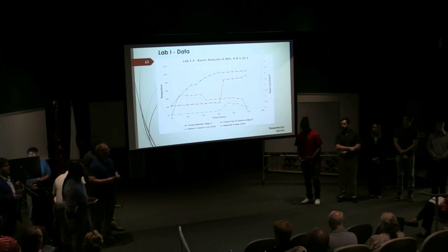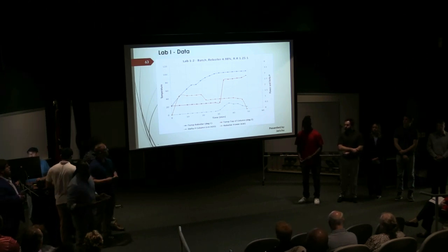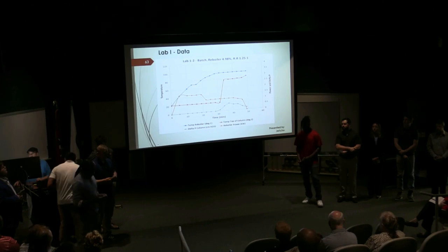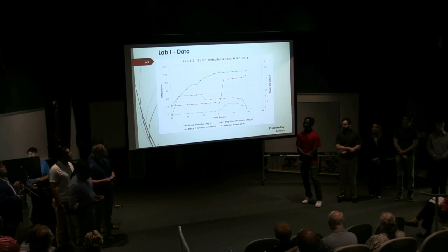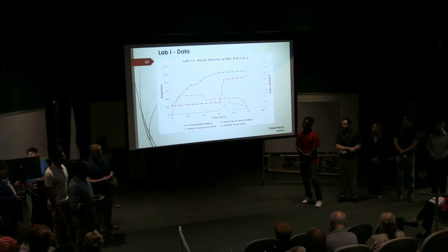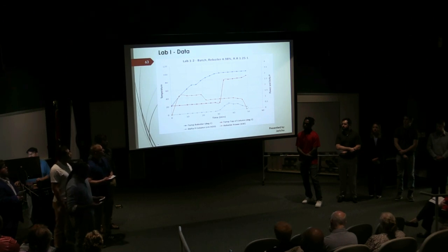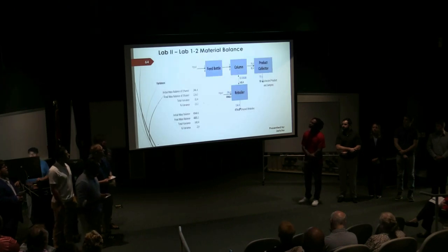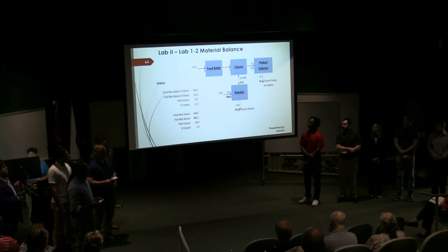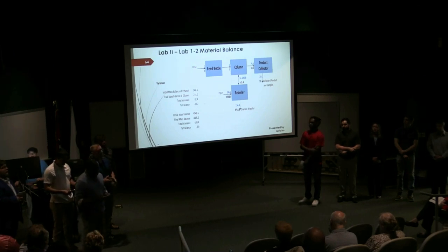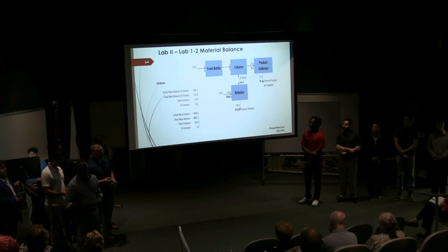In our next experiment, we raised our reflux ratio to 1.5 to 1. And looking at our data, this run was a little more stable. We did not collect product for 15 minutes, despite lowering the reboiler temperature. Also, our pressure drop curve is indicating higher production rates at the beginning of the run rather than at the end of the run. Ethanol variance on material balance was higher than we desired. Our overall balance was within target. We think this is due to measurement errors for one or more of our concentrations.